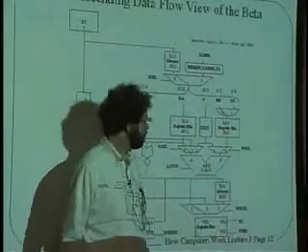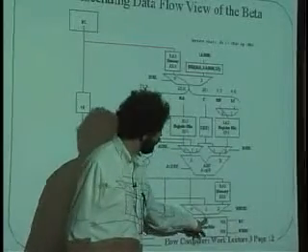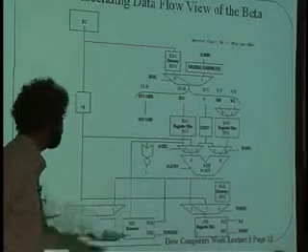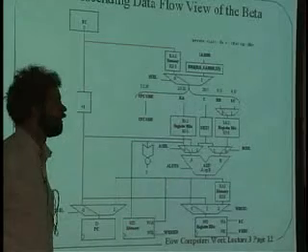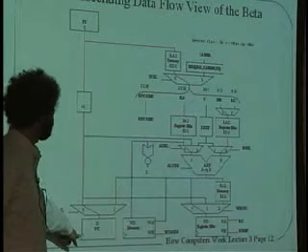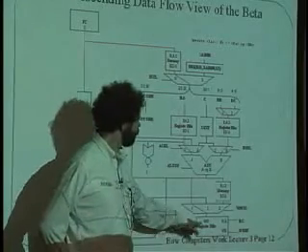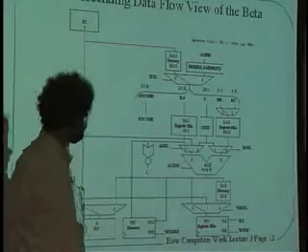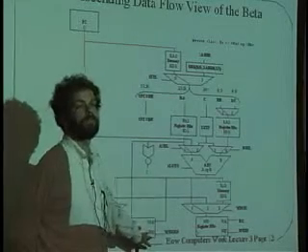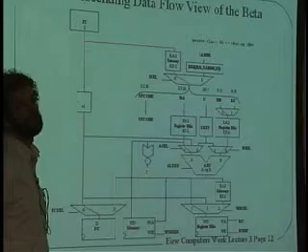Okay, that goes high because, in fact, the register C code is put into here and the data that is supposed to go into register C gets put there, and finally at the end of the cycle when the clock goes off, click, and all three of these things take their, or try to take their picture at the same time, what will happen is the PC will get the value of PC plus 1, and the register file will get the new value that's supposed to go into register C. And this guy over here, with WEMEM being low, will do nothing, even though the clock goes off. And that's how we do RC equals RA plus RB.